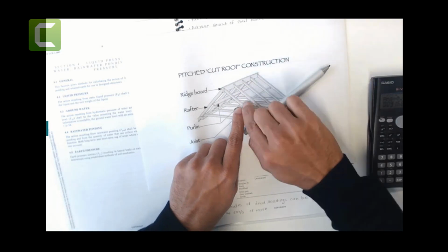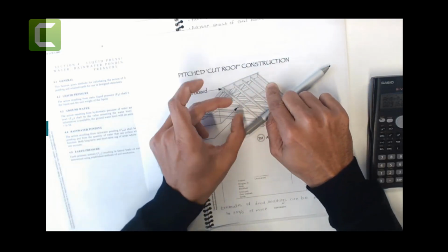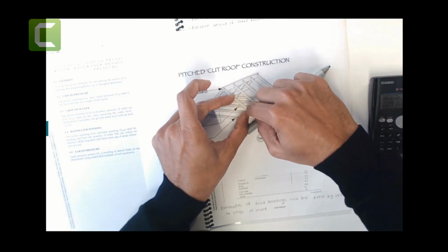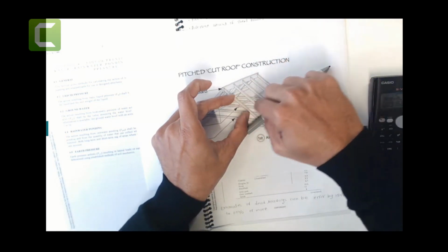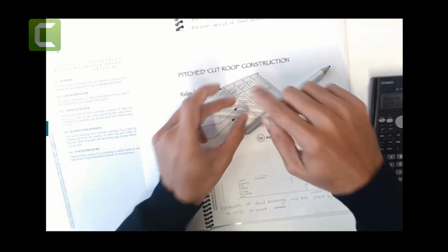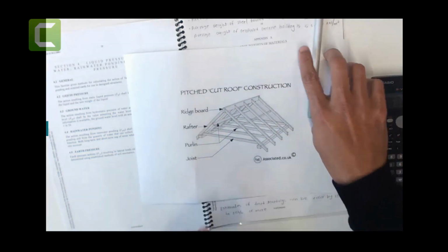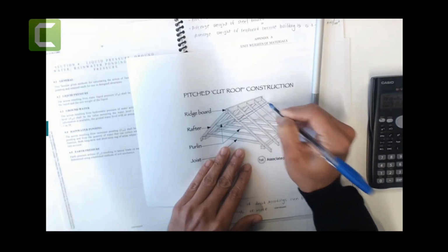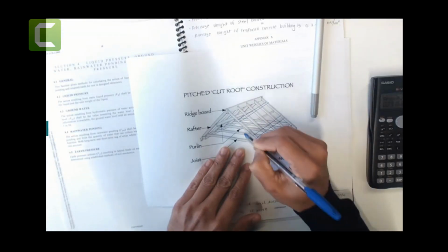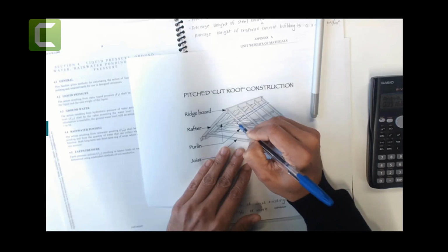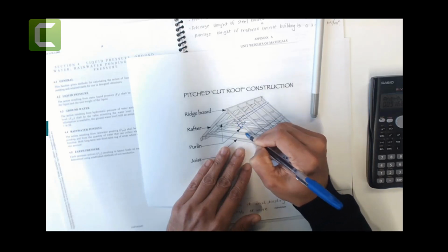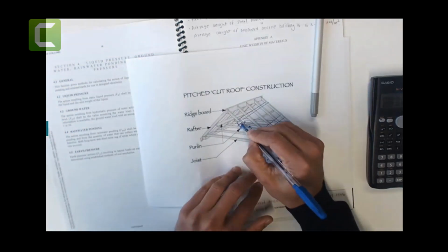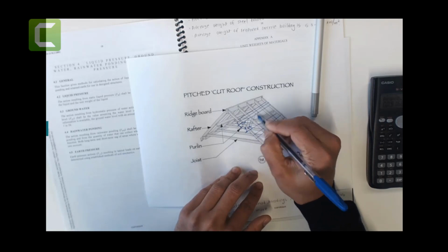So these UDL loads which I'm going to apply here, I need to convert into pressures. So I need to take the center to center distance. And by the way, there is a purlin going here and a purlin going here. So half of 450 here, half of 450 here. That's how it's making 900. So this will become the tributary area for this one.